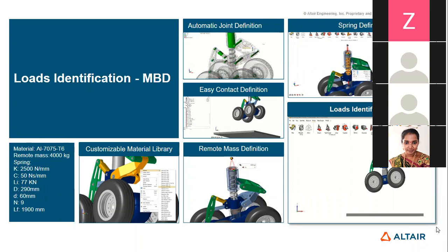Then once you bring your tentative design of the shaft with 100 diameter to the software and apply the load and the boundary condition, the software will suggest you have selected a lot more material for your component. Basically, for that load, such a big diameter is not required. So the software will automatically scoop out the material from your shaft and suggest some optimized designs.